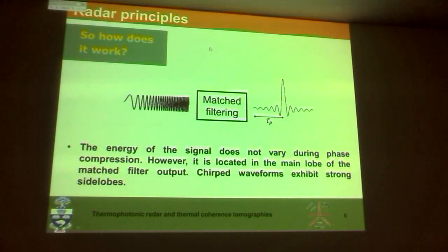And thermal diffusivity is a dynamic parameter. When you have a cold cup in your hand, and then you put hot coffee in there, how long it's going to take before you feel the heat depends on the thermal diffusivity of that medium. The higher the thermal diffusivity, the earlier you're going to feel the heat in your hand. So this is dynamic, because heat propagates.